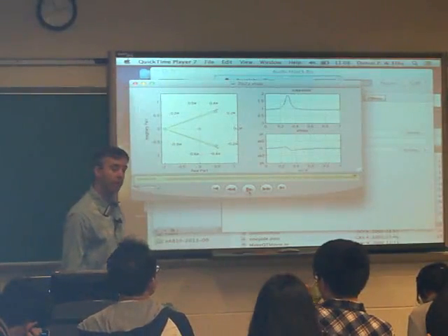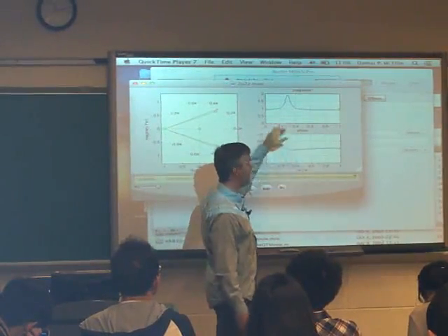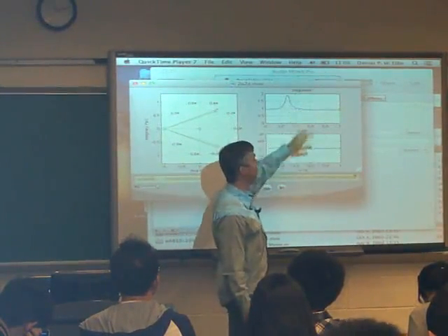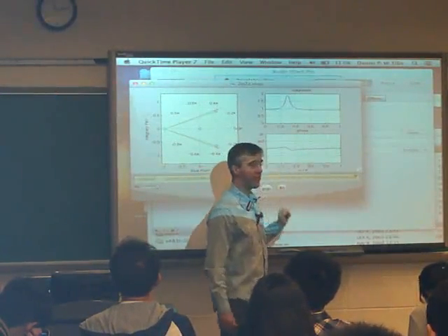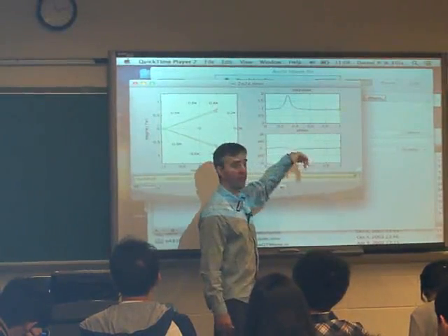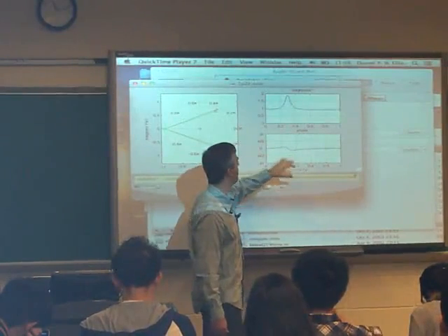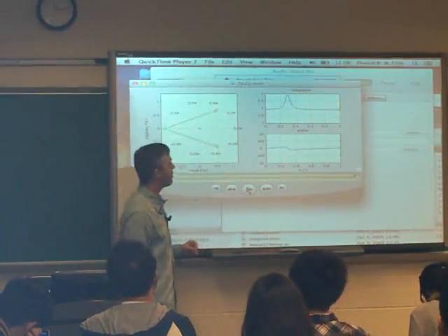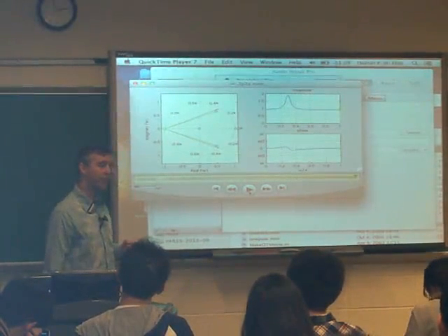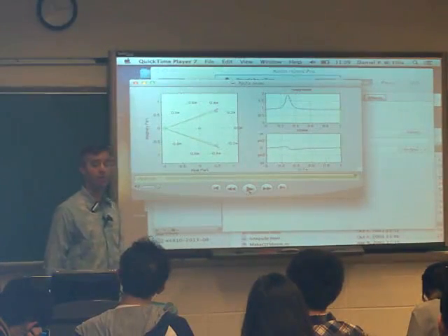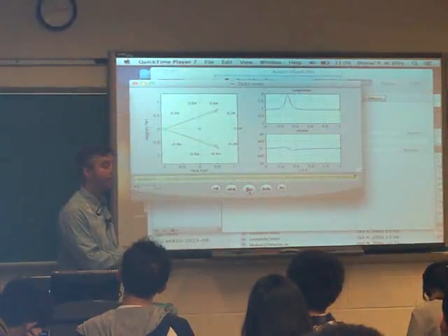This is quite an interesting system, right? The system where most frequencies are more or less unaffected. They have a gain about 1, a phase about 0. But for some restricted range of frequencies, suddenly the gain becomes larger. The gain is significantly different from 1. Phase is still around 0, although it's not quite so close to 0 as it was at the other frequencies. So this is now beginning to look like an interesting thing, even though it's only got 2 poles and 2 zeros, and is not a particularly complicated thing to calculate in the time domain.